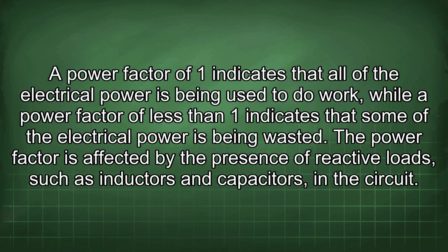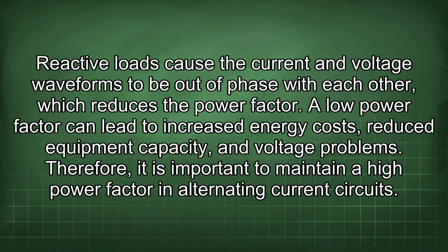The power factor is affected by the presence of reactive loads such as inductors and capacitors in the circuit. Reactive loads cause the current and voltage waveforms to be out of phase with each other, which reduces the power factor. A low power factor can lead to increased energy costs, reduced equipment capacity, and voltage problems. Therefore, it is important to maintain a high power factor in alternating current circuits.